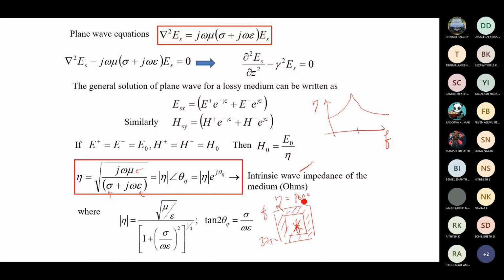So substituting this frequency and the impedance, we can get the ratio of the sigma, mu, and epsilon. By choosing one value, we can get the other values and then we can design such a material. Therefore, if you coat this special material which shows a wave impedance of 1000, which is actually very high,